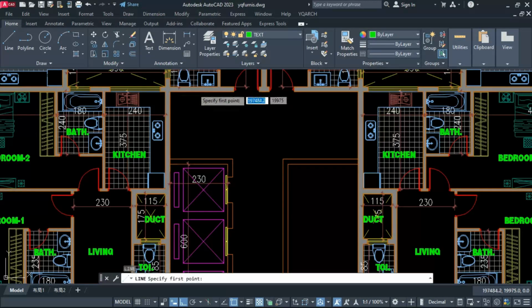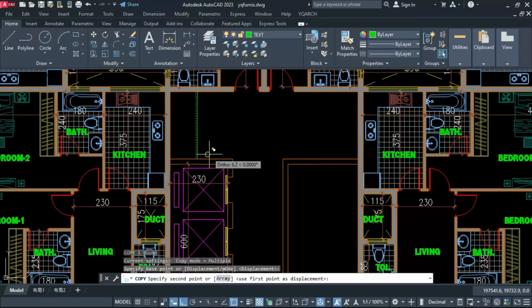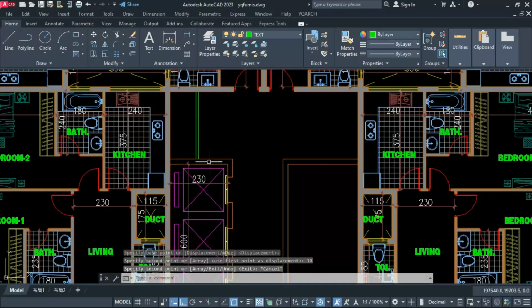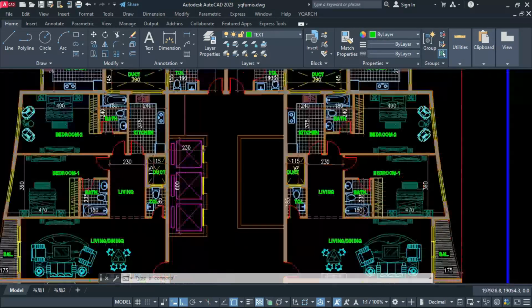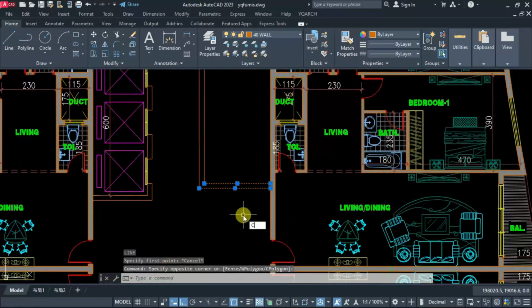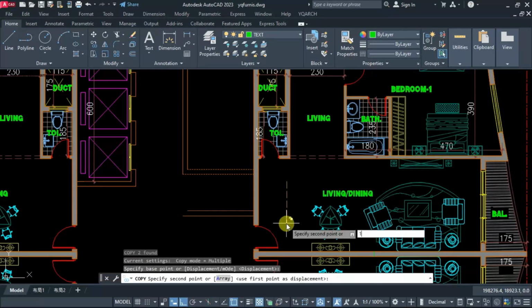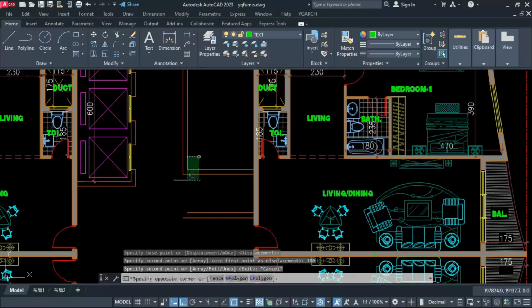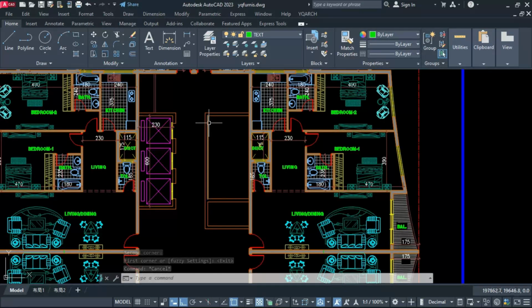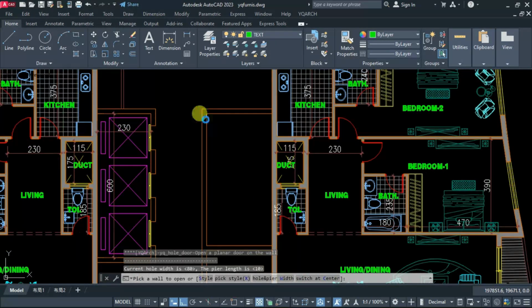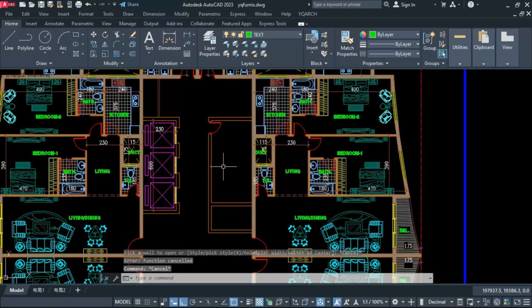Now, here we can keep a fire cabinet, but we are getting wider space. Means dead space you cannot keep like this. Okay. You must arrange, you must utilize that area. This is our staircase. We have provided duct also. We have to provide service duct for this staircase. Now, we'll place the staircase here. AD command. This door we are getting.